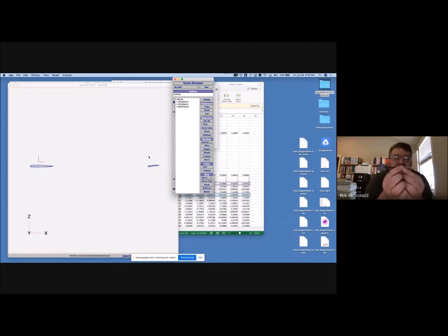And what you'll notice is it's got the tail in the back, right? The fins are in the back, and the center of gravity is somewhere way up here in the front, because you've got this big brass section. So all the weight's in the front and the tail's in the back. And the reason you do that is because it's going to pivot around the center of gravity, and the fin in the back means that its aerodynamic center is all the way in the back.